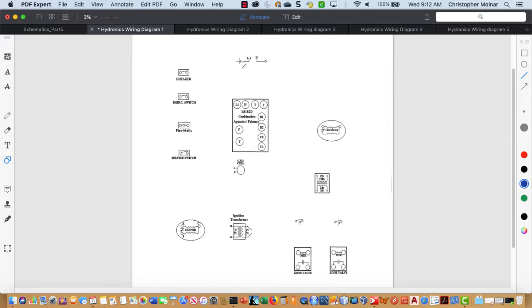So from our power source, we have to start off by going to our safety switches, okay? You cannot bypass the safety switches. And safety switches are all wired in series, which is why you see me going down here and doing we're going to connect everything in series. If one switch is open, nothing else will get power. Okay, coming out of our safety switch from L1, I am going to come up and I'm going to connect into the terminal L1.